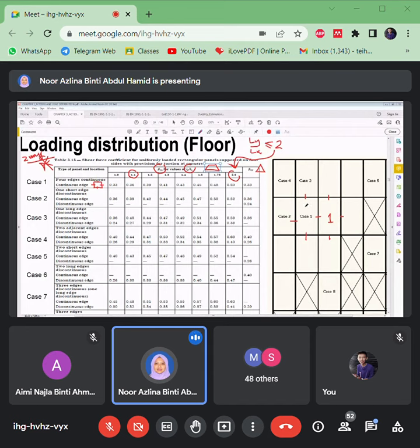So you make lines parallel to the longer span, making triangles. Remember, this trapezium is a BVX. Let's say Ly divided by Lx is 1.1. So that means the continuous edge is 0.36. So this is continuous, right? So there's a coefficient for the continuous edge and there's also a coefficient for the discontinuous edge.